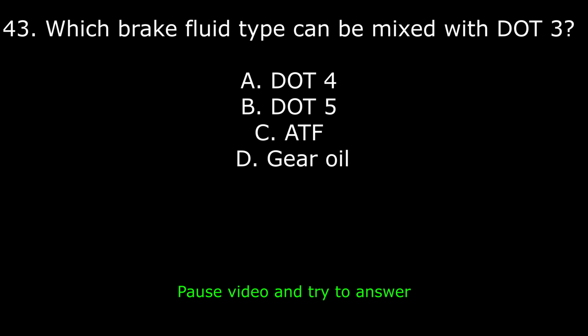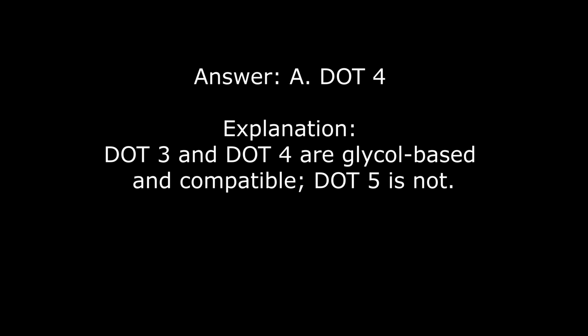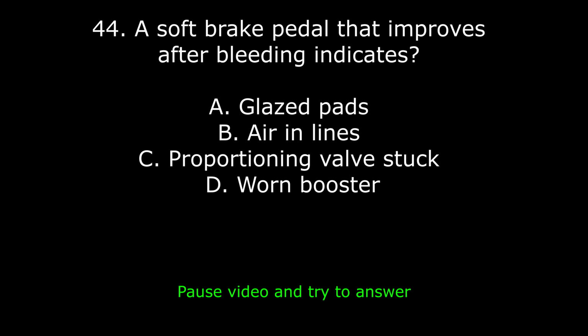43. Which brake fluid type can be mixed with DOT3? A. DOT4, B. DOT5, C. ATF, D. Gear oil. Answer A. DOT4. Explanation: DOT3 and DOT4 are glycol-based and compatible. DOT5 is not.